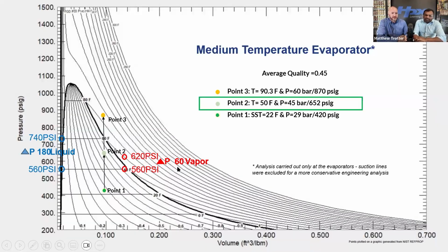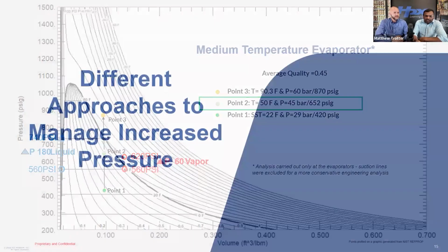So that's why with the vapor it's sensible, not really doing anything. Yeah, not doing anything. So that's why we say, okay, for the vapor you will have more time. Even if you lose the power, before the pressure hits the relief valve you will have hours, 6 hours, 8 hours, 10 hours, depending on the location and ambient conditions. But for the liquid, if the receiver is outside on the roof, the pressure can go up quickly, the temperature can rise, right? So that's another thing that we are going to look into for mitigation, how we mitigate that.